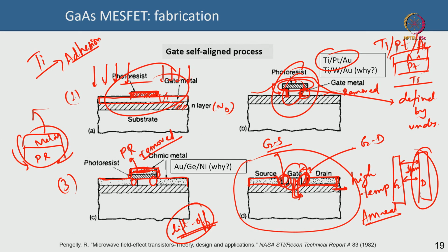Now basic semiconductor physics tells us that the metal work function matters when you are putting down the gate metal. For a Schottky contact you need a so and so work function, etc. However, in gallium arsenide or aluminum gallium arsenide surfaces there is something called Fermi pinning, which means there are defect states and donor like states on the surface which will pin the Fermi level, or in other words your Fermi level position will be fixed at a certain value in the band gap, and your gate metal work function, whether you are using a low work function or a high work function metal, does not matter. Your Fermi pinning dictated by the traps and defects is what matters.